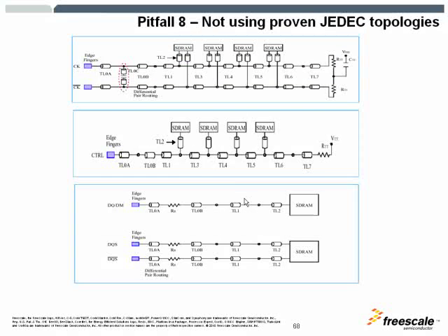Only use the topologies that are approved by JEDEC. There are many ways that you can route your DDR subsystem, but please do follow the JEDEC approved topologies.